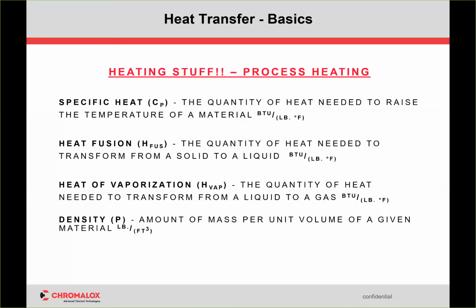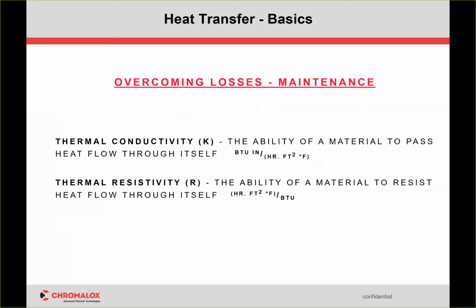So there's heat of vaporization. If you're doing a boiling application or a vaporization application, that's the heat of vaporization. And then the density, which is the mass you're heating, the amount of molecules, plus the specific heat of the molecules, and then your delta T is essentially your equation, which is pretty straightforward.